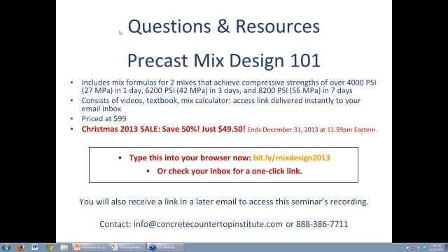Next question. Do you recommend using 20% of pure CSA as a replacement? No, I don't. Will that achieve a strength advantage? It might, but it just makes your concrete really complicated. It's going to make your concrete set really fast, and you may not be able to deal with it. Does the face coat and backer coat have to be dosed at the same rate? If it's pigment, no. If it's superplasticizer, no. If it's polymer, yes. If it's fiber, well, no, because the face coat doesn't have glass fibers in it.